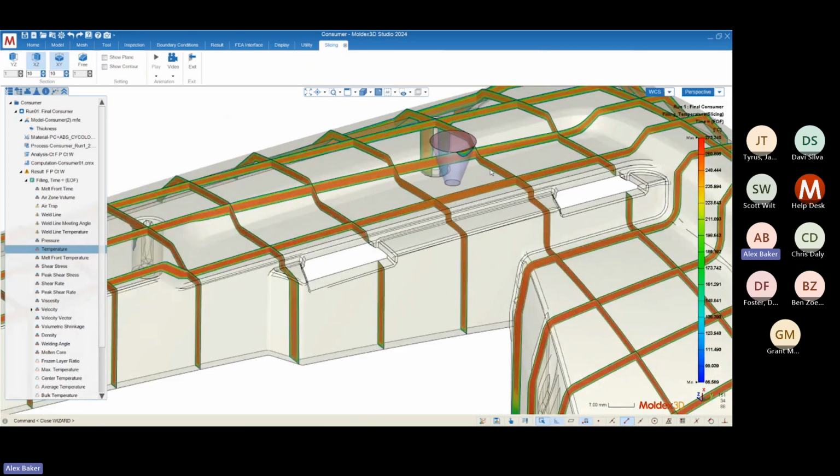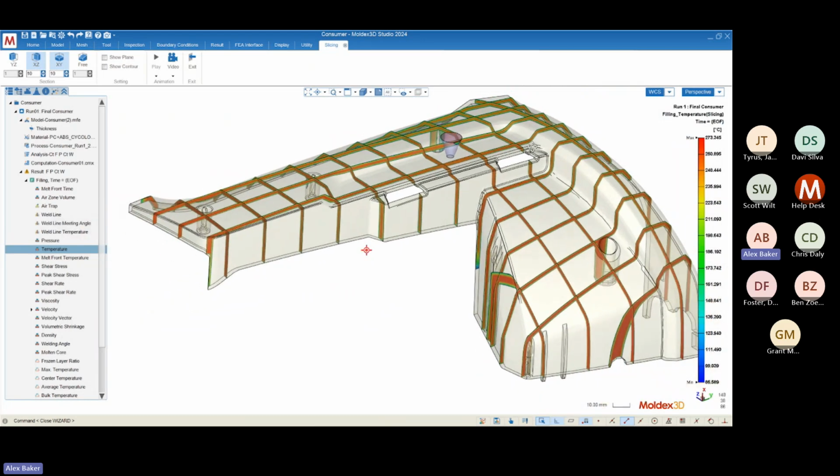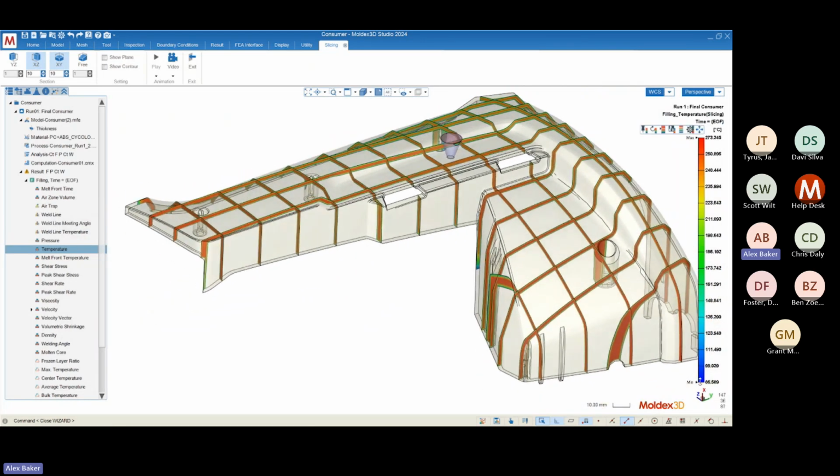Now, the entire core of my geometry is really up towards the top side of my scale, obviously, because that's where the hottest material is located. So I'm going to change the extent of my scale. Since I'm really only interested in the top portion of my scale, I can bring the bottom of my scale upwards, like what we did for the thickness distribution earlier.